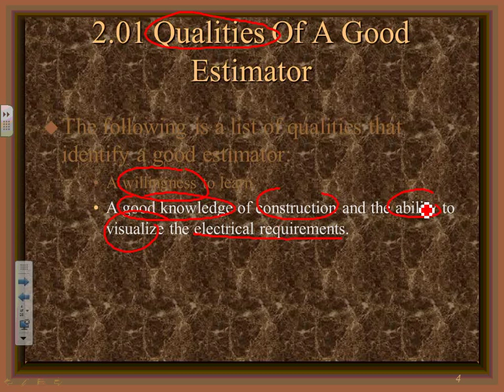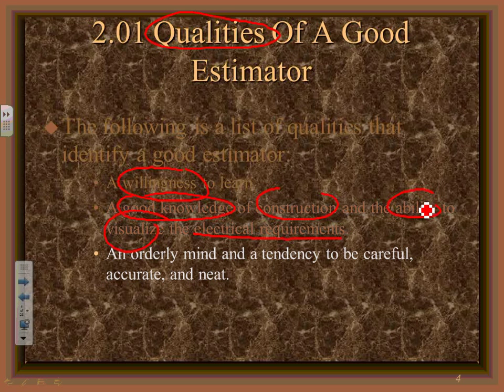So visualizing electrical installation. If you guys don't know that to go from this wall into this wall, I have to go up, over, and down again, you're not a good estimator. So when you're looking at the blueprints with your friend Chad, when you're measuring, when I come and review it with you guys, I want to say, have you accounted for going up 9 feet, or whatever we said, and down 6 feet to the panel? So that's visualizing how the branch circuits and the feeders are going to actually physically, mechanically run from point A to point B. So that's another thing you ask yourself.